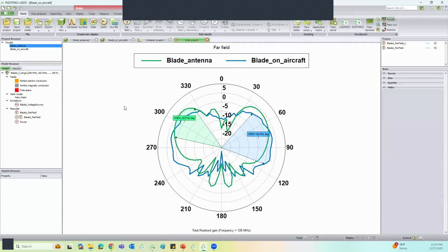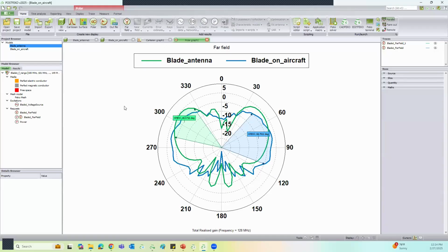So this way, you can always do a basic antenna analysis, or if the desired antenna is not meeting the specifications, then you can set up optimization, fine tune the design for the specifications, and then do an antenna placement analysis. When you do the antenna placement analysis, let's say you need to make some changes with the platform, that is also possible.